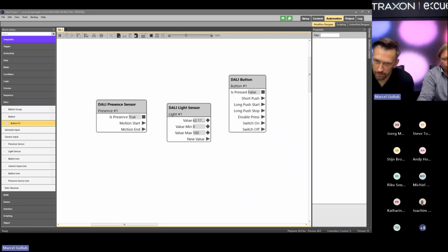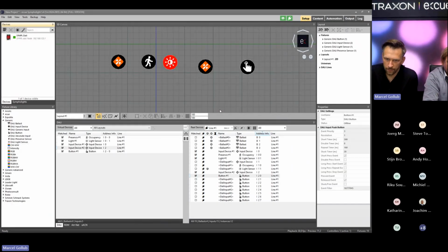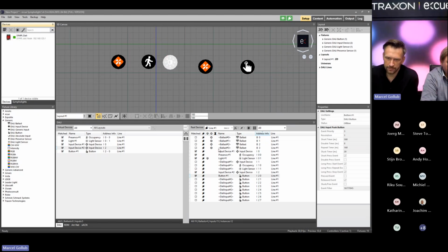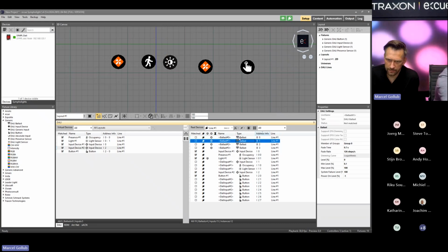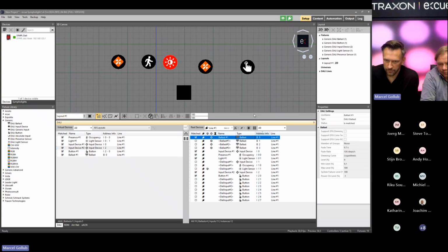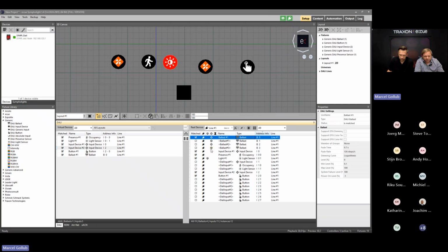So the integration is really straightforward. The relays will simply be detected as ballast. If you scan the bus, you will detect 4 ballast, the same way as the sensors and other devices. You can easily drag them into the canvas, and then with a value between 0 and 100%, you can control the relays. If 0, then the relay is open, and above 90%, it switches on.